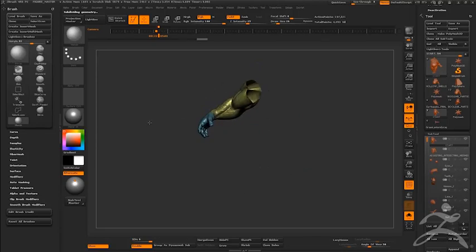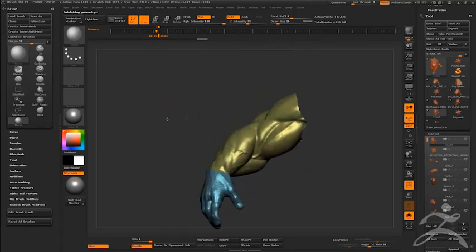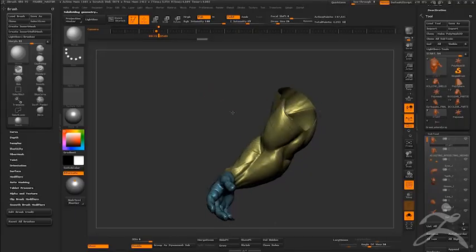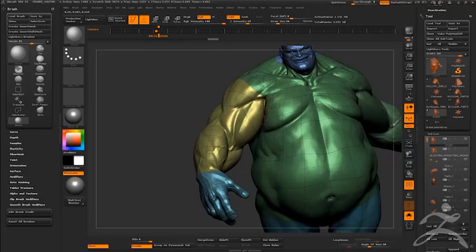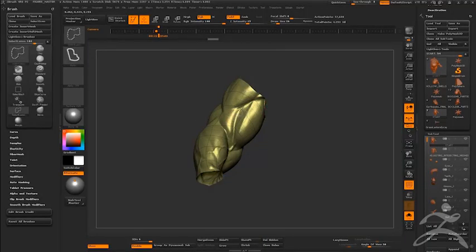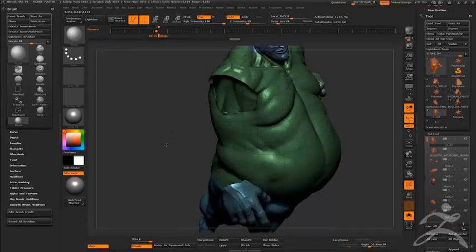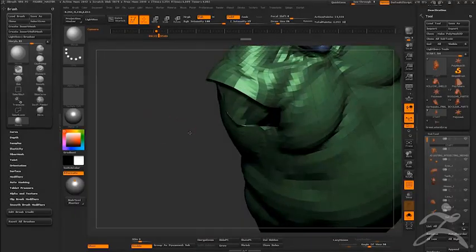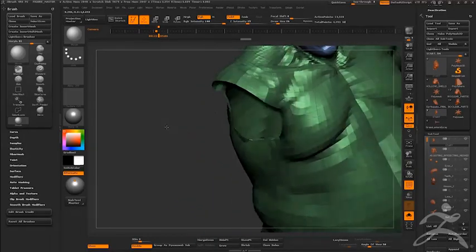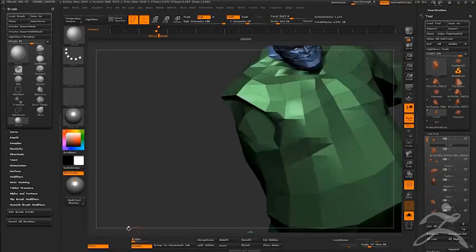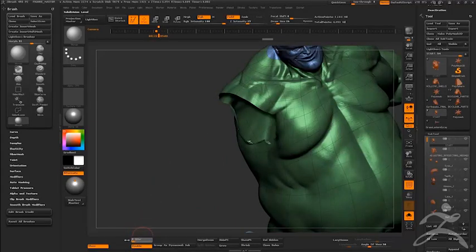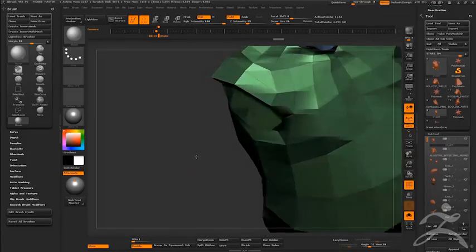The rest of this figure here, I'll leave intact, and I just want to deal with this arm right here. Well, I can very easily split this off on its own, but there's going to be issues. I come back here, where this arm is intersecting the model. You can see that there are some very strange, weird, interpenetrating parts here that you really need to clean up if you're going to have a joint there. So, the nice thing about doing this in ZBrush is you have the freedom of going up and down in subdivision history to very easily make adjustments at a lower level.